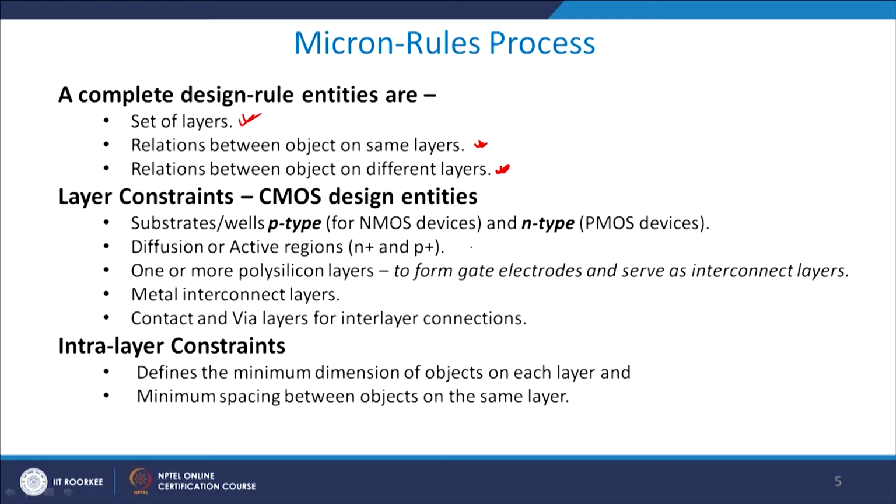So in this case we have layers. For example, you have an interconnect layer, which is the metal layer, then a polysilicon layer, then a field oxide layer, then a silicon layer, and so on. At each layer we start defining the distance between 2 active points or 2 passive points. We can also define the distance between 2 layers across a particular board. So what are the constraints?